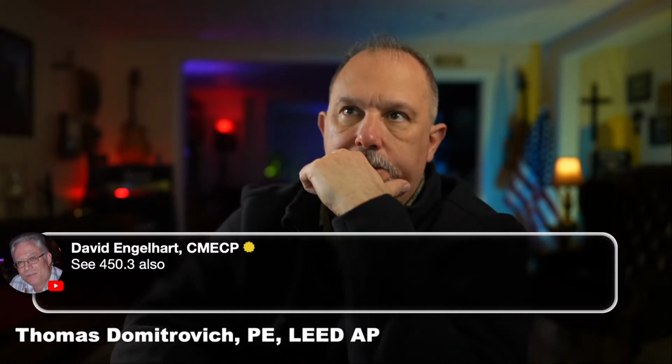See 450.3 also. Let's check out 450.3. Now what we're doing is giving you the code reasons why. 450.3, overcurrent protection of transformers, has to comply with A, B, or C. A is transformers over 1,000 volts. B is transformers 1,000 volts nominal or less.